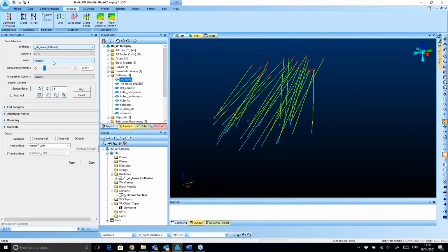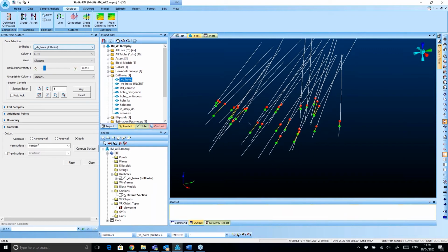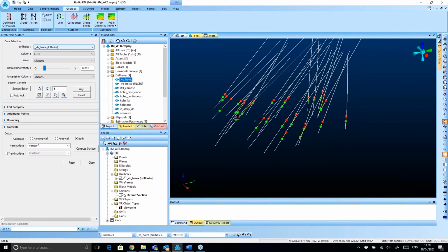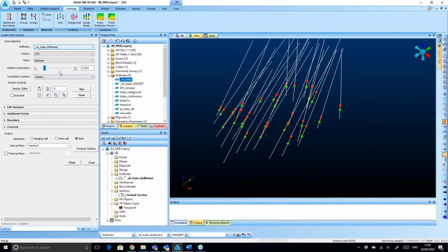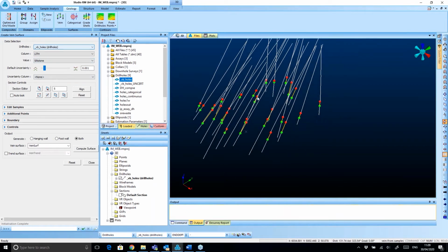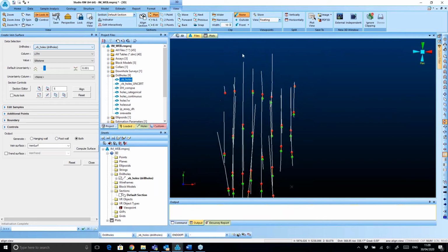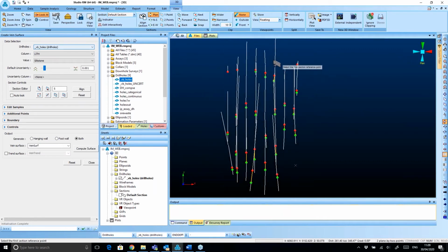Then after that, I have here the attributes, lithology codes, which came from my drill hole file. Yeah, and then I have basalt, breccia, sandstone, siltstone, soil. Let me use siltstone. And then the system automatically recognizes all the intervals of siltstone. You can see here. Then if I go, for example, now to the section view, then you can see them probably better.